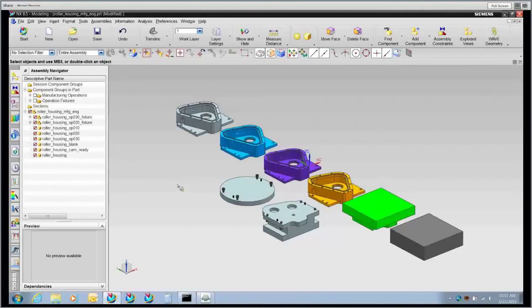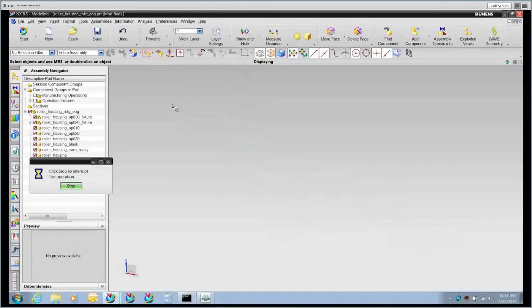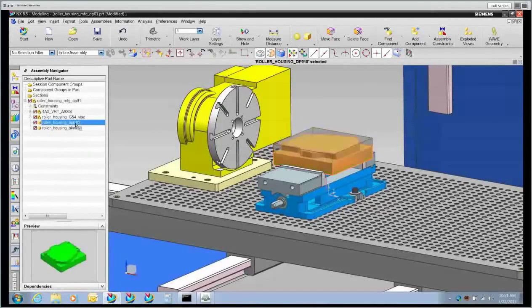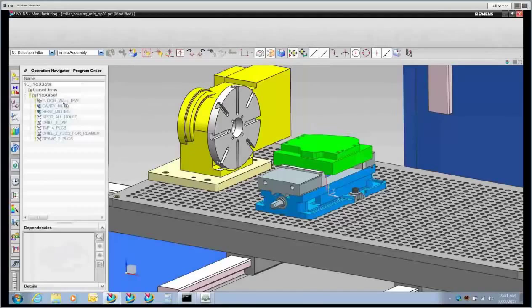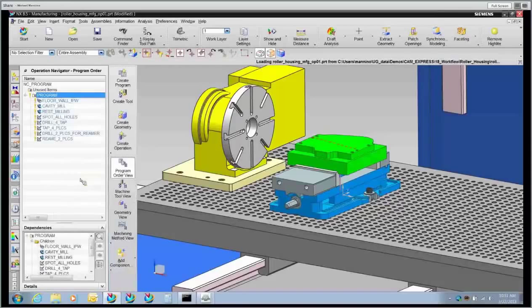Okay. From here, we can create manufacturing assemblies for each operation where we take the individual in-process workpieces and load them in. Have that already here. So you see here in the first operation we have the blank and the operation 010 assembled in. Go ahead and turn the blank off for now. Go to manufacturing. We have a program that makes the part.